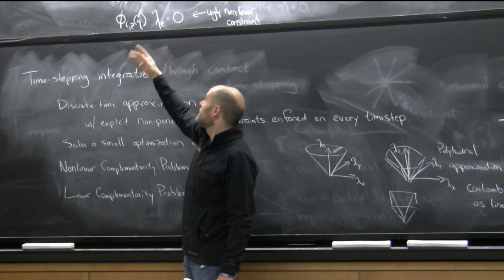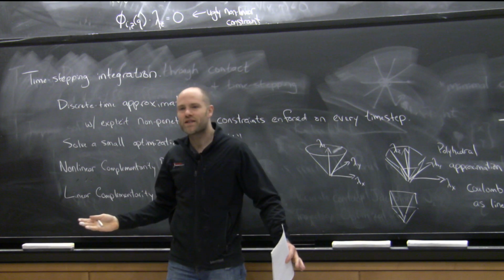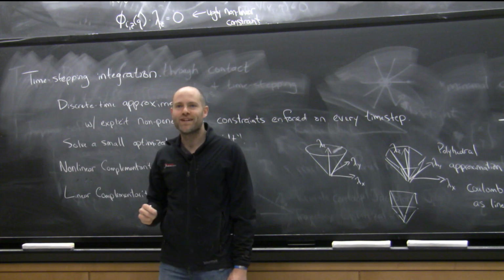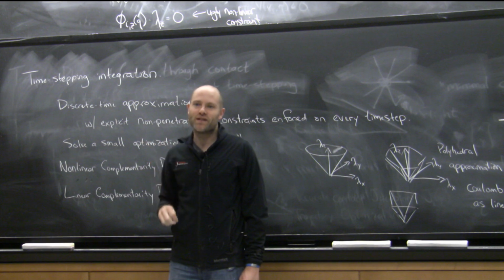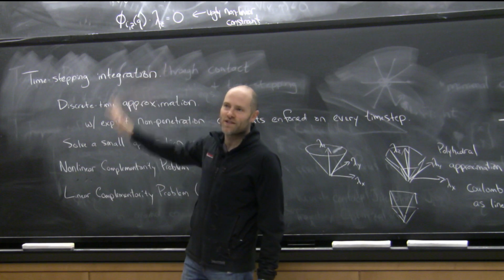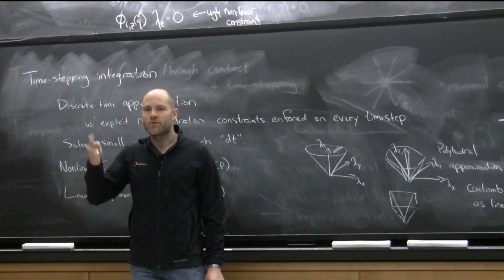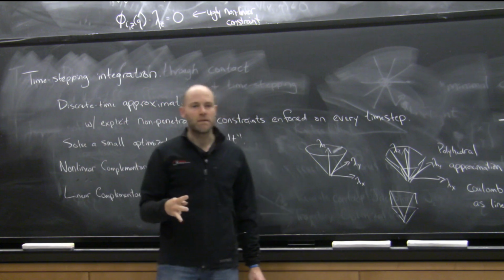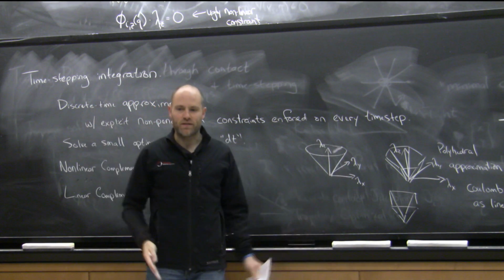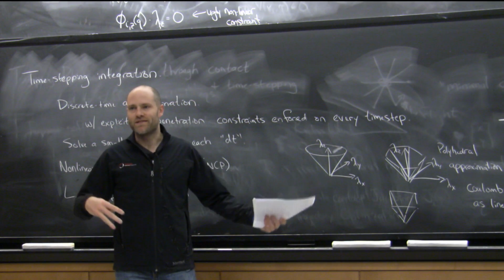So what the solvers do in practice is they say, there are 15 possible constraints that could be active, I'll choose 3, because you want to have a fixed runtime, right? There's some number that's hard-coded. It says, I'll take the 3 that look good, enforce those, and solve a fixed-size LCP at a consistent runtime in order to get an interactive experience for people. I think that's justified, but that's another reason why things blow up. But the bad thing is that our robot software does that too.